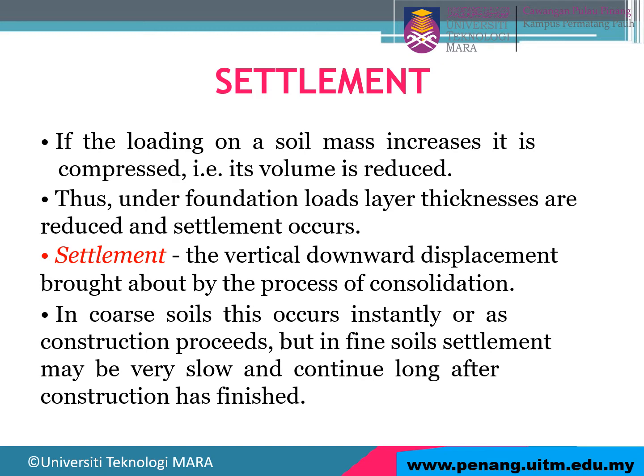However, for fine soil, the settlement may be very slow and continue after construction has finished. So it means that this is a long process. That's why we have to determine the settlement after 10 years, 20 years, and 30 years. We have to predict the settlement so that our building or construction does not fail.